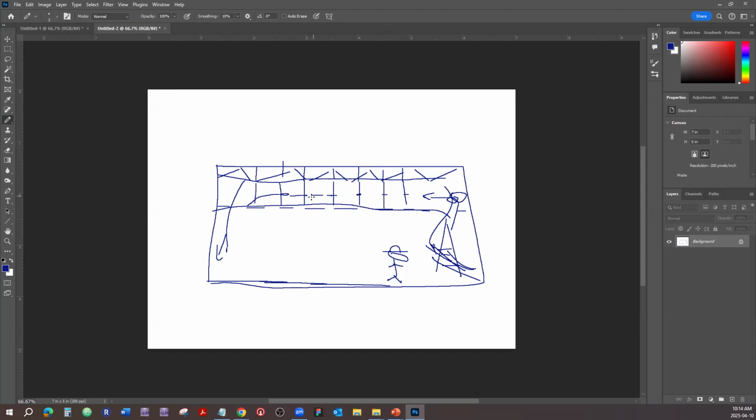That is a big no-no. We are not supposed to do that. Any wiring should be tied to the red iron if you can. And if you can't, there are those J-hooks that we're going to talk about in the next couple of slides. J-hooks that are suspended on, let's say, threaded rods, or use cable trays or any other kind of raceway, as long as those wires are not tied to any of the ceiling structures, especially to the rods that are hanging from the ceiling and are supporting the ceiling tiles frame.